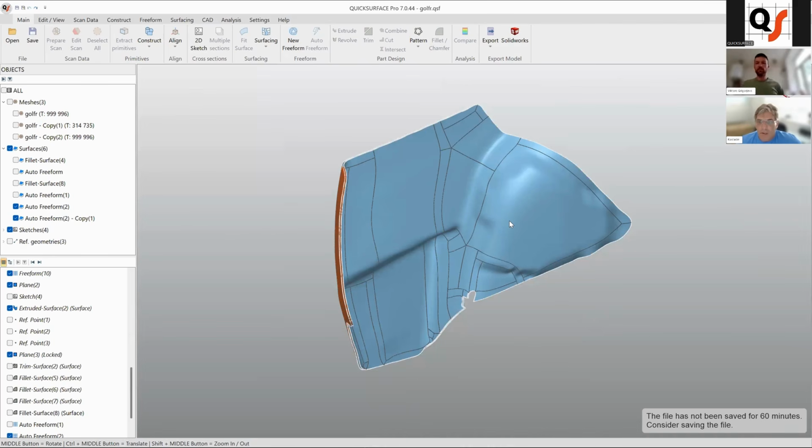This is the fundamental thing about the number of control points in the CAD industry. If you want to make a really good and smooth surface, you must keep the number of points as low as possible, ideally a maximum of 3 points. This is the perfect smoothness. Of course, it's not always possible. That's why we have continuity, G1, G2, G3.